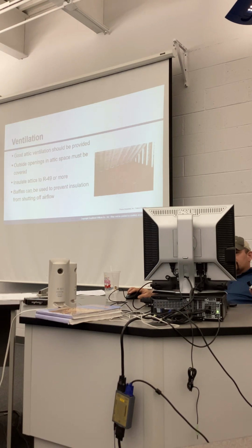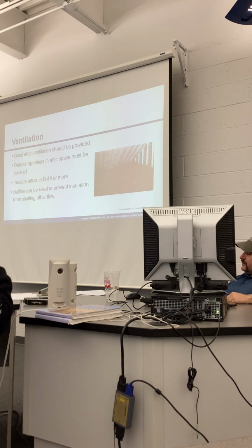So when you put that vapor barrier down for your concrete, so that basically you're insulating. No, the vapor barrier is doing what it's doing. It's eliminating vapor. So your floor will sweat. Concrete will absorb water. It acclimates to what it's around. So if there's water under the slab, and then you heat the inside, the water will come up through the concrete and sweat on top of the concrete. So you get water. That's why we put the vapor barrier.